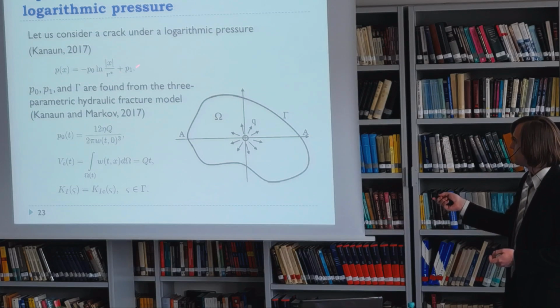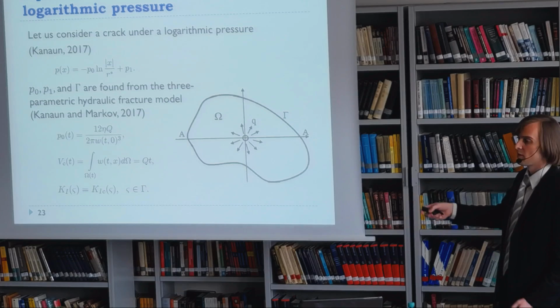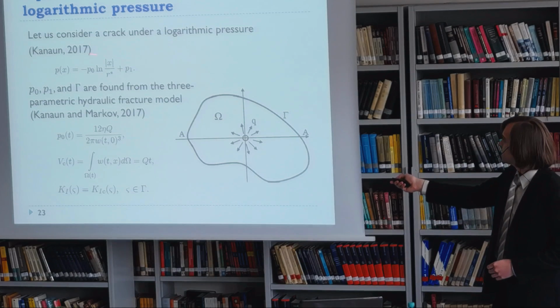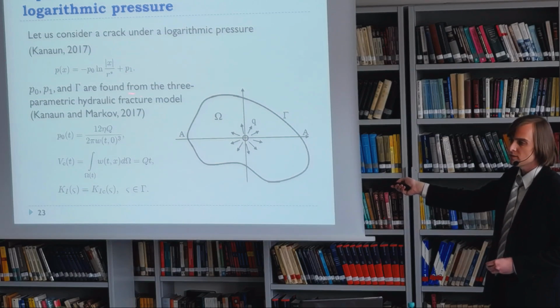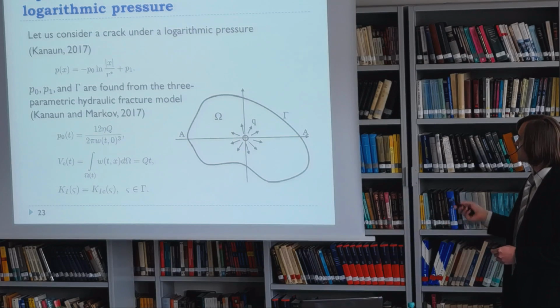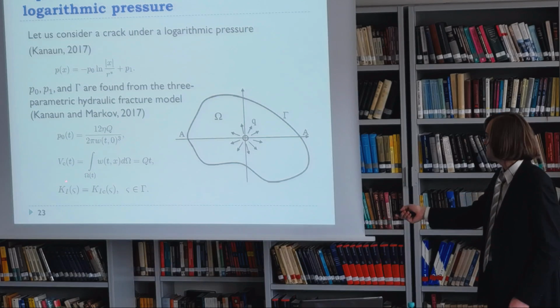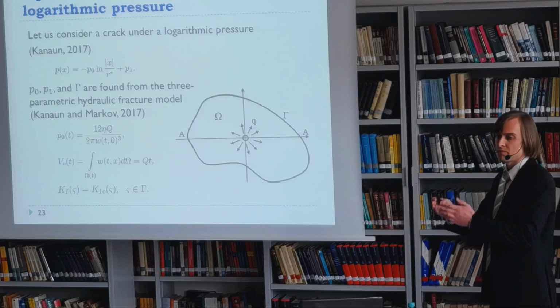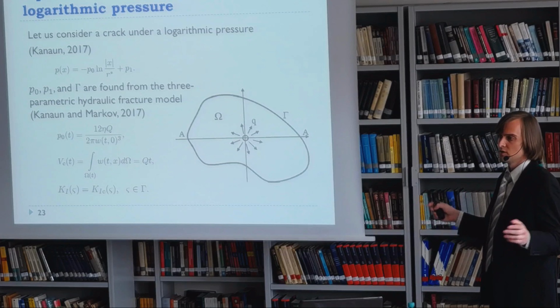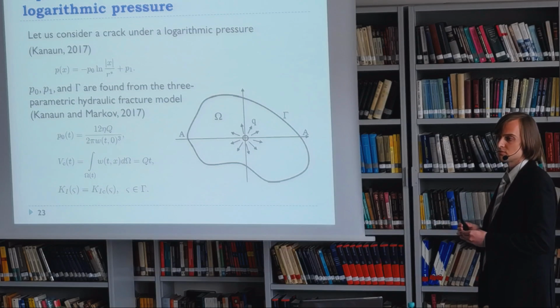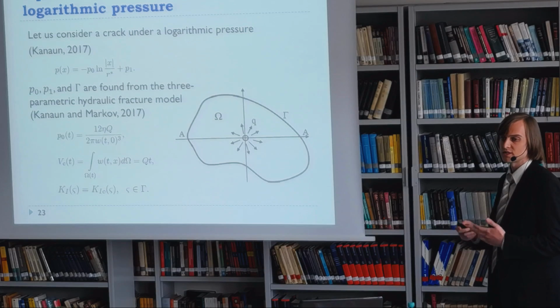So we simulate the hydraulic fracture, with the pressure of the liquid as a logarithmic one. First of all, it should satisfy the Poiseuille equation and of course the flow equilibrium, and at each step, because the hydraulic fracture growth is basically quasi-static.